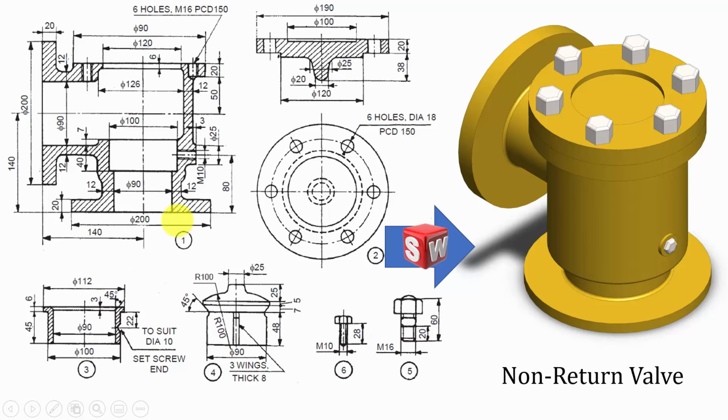So first I am going to start with the body, that is part number 1. Here I am going to draw this section and revolve it. This is an added section, so you can see here. Initially I am going to neglect this extrude and consider this as a straight line and model it. In the last stage we can draw this extrude.